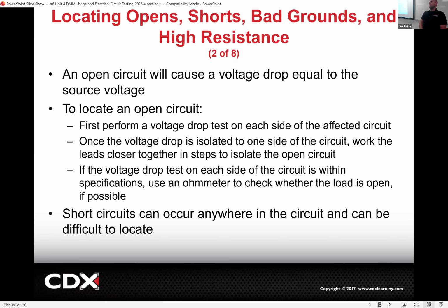So if the car came in with the taillight bulb being dim, I would suspect that's going to be a high resistance. Cool. So I already know my story is going to say high resistance. Where is it though? I don't know. I've got to test it.